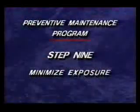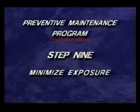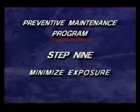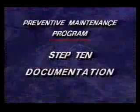Step 9 is to minimize the amount of time your aircraft is exposed to adverse environments if at all possible. This is perhaps the best way to prevent corrosion. If you have access to a hangar, use it.